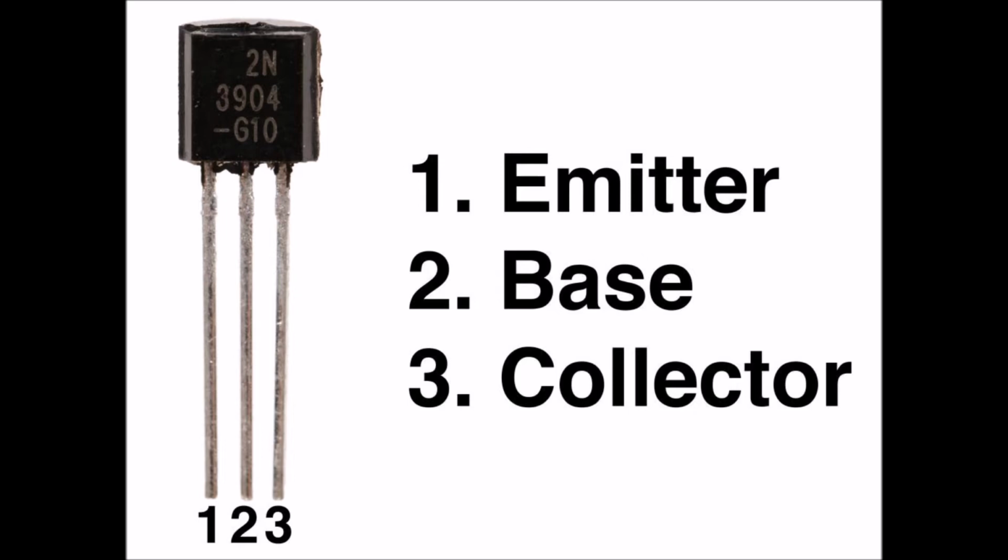The signal enters the transistor through capacitor C1. Resistor R1 keeps the input signal from shorting out to ground. Resistors R2 and R3 provide the base bias. Capacitor C2 holds the base at signal ground. Resistor R4 keeps the output signal from shorting out through the power supply. We get the output through capacitor C3. The common base circuit exhibits a relatively low input impedance and provides somewhat less gain than a common emitter circuit.